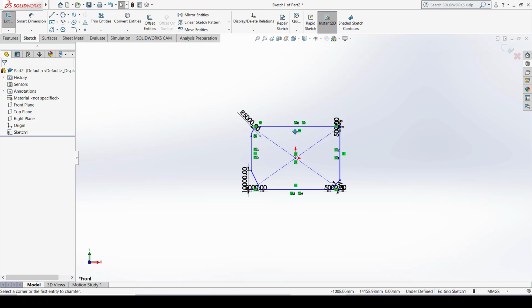So these are basically all the basic element structures, and you can see how to draw them in the 2D module of this software: line, circle, rectangle, arc, slots, polygon, fillet, chamfers, ellipse and splines. These are basically the elements used to create a proper drawing. You can use lines to create straight lines, arcs to create fillets and so on.